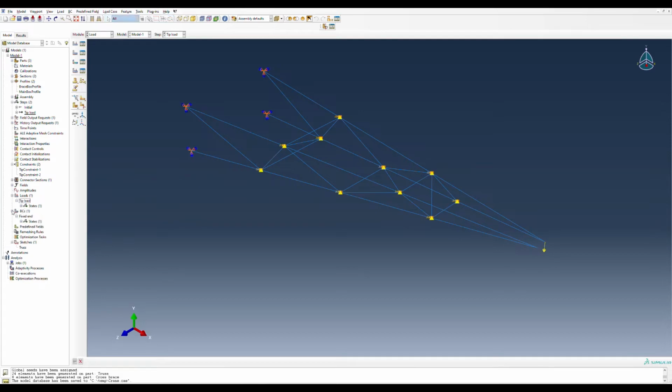And then our boundary condition, we're going to make sure that this is a fixed end. Now make sure. Okay, yeah, so fixed end, 1, 2, 3, 4, those 4 points are essentially acting like a wall that is connected to. This boundary condition is really helpful because once the load is applied, it becomes uniform across tip B and tip A.